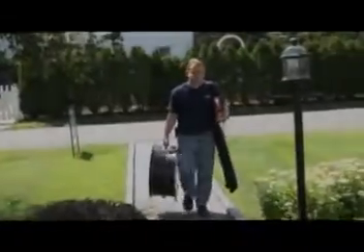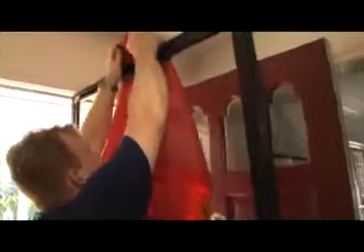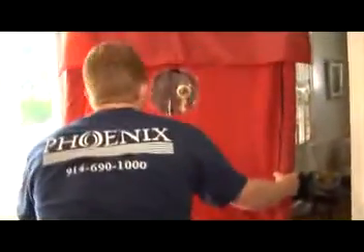The blower door test, a critical element in any home energy audit, will determine the air tightness of the home and locate the sites of air leakage. After closing all the windows and doors, Larry installs a giant calibrated fan, creating a pressure difference between the inside and outside. This will force air through any holes or penetrations in the house, which can then be measured.